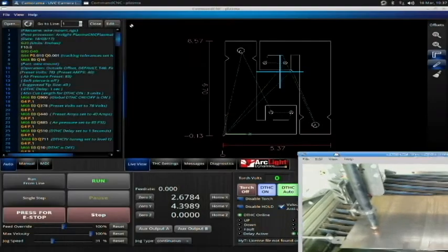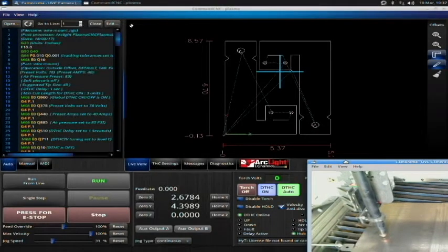Okay, so for starters, what I'm going to talk about is doing a dry run. Okay, so currently I have my machine set up. I have my plate on, and whenever you do a cut, you want to do a checklist, because there's a bunch of different things you have to make sure are properly set in order for you to get a good cut. Number one, you want to say, okay, table's turned on, it's powered up properly. There's nothing in the way of the motion of the gantry. There's nothing on my side rails that is going to cause a problem in this motion.